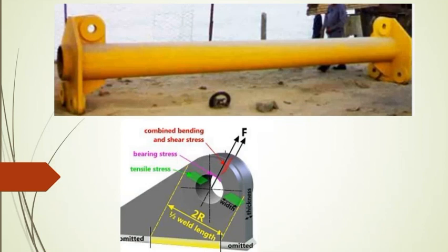One sample spreader bar you could see here. It has lift points, and below also we have lift points. This spreader bar is mainly to spread the load. When we have a structure with a lot of equipment and we want to keep a clear sling passage, we use the spreader bar to spread the load, and from here the slings will be connected onto the hook.